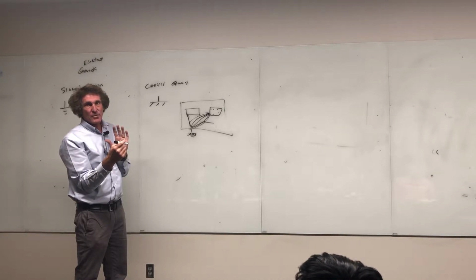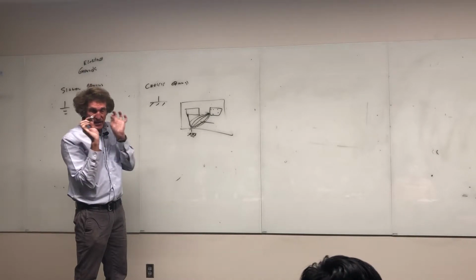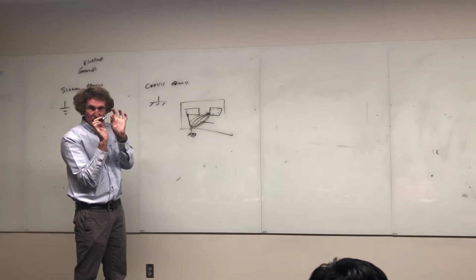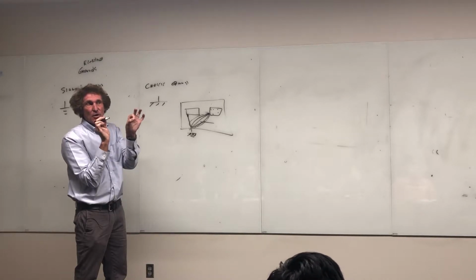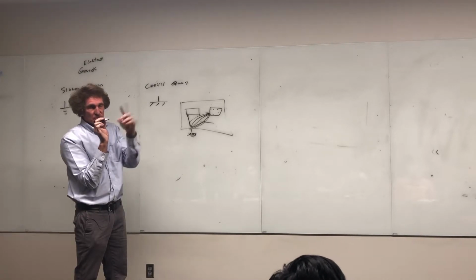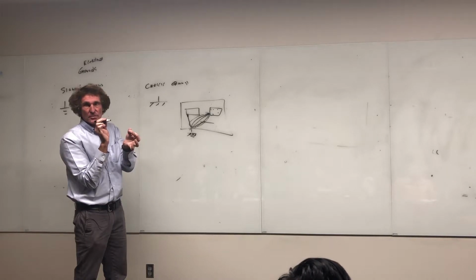But you've got to be careful when you do measurements to keep the leads as close as possible to the points where you want to measure. And always make sure if you're going to use a single ground, it's on the board you're trying to measure, the smallest, or the actual FR4 board or something like that. Don't put it to the bottom of the chassis.